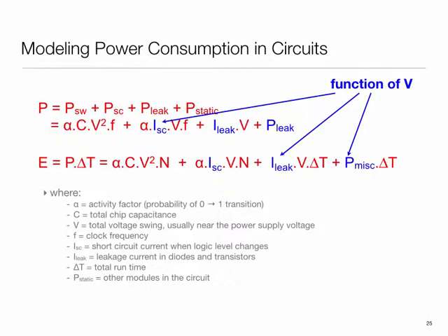Then there is leakage current, which happens because deep down the semiconductor devices leak at the various diode junctions, and this is happening as long as you are powered up. So there is no dependence on frequency. Even if you stop the clock, this is still happening.